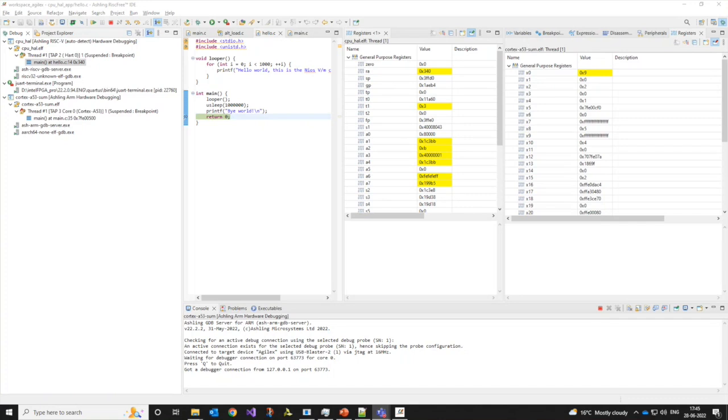Okay, let's see. Another follow-up on the question about hardware breakpoints. An individual added some more clarification to that. Are hardware breakpoints available when using this? The answer is yes. The current Nios 5 core exposes one hardware trigger register currently, so one hardware breakpoint can be supported in the current architecture. So there we go, we have one hardware trigger register currently in the Nios 5 core.